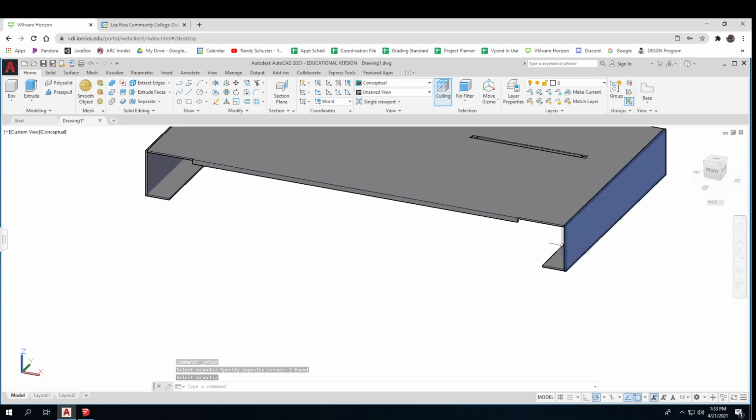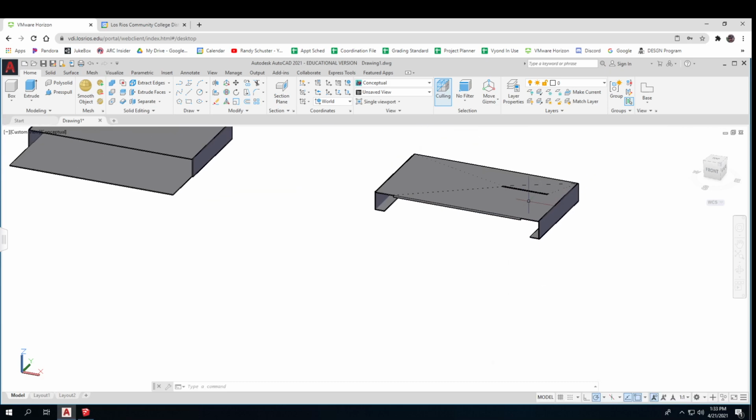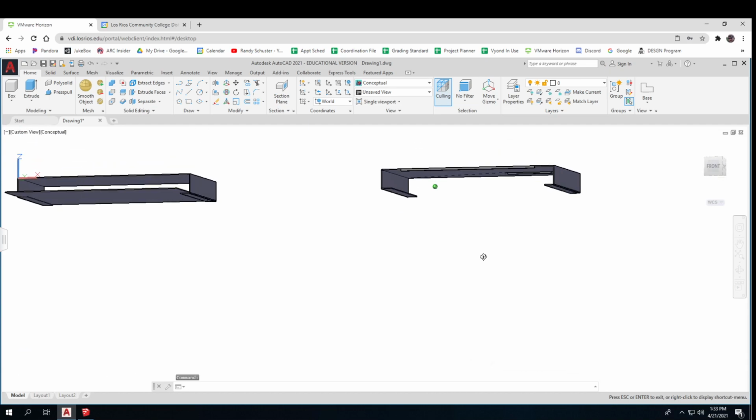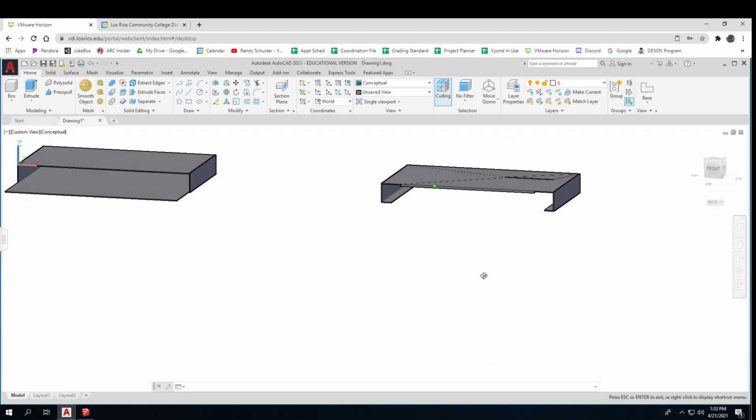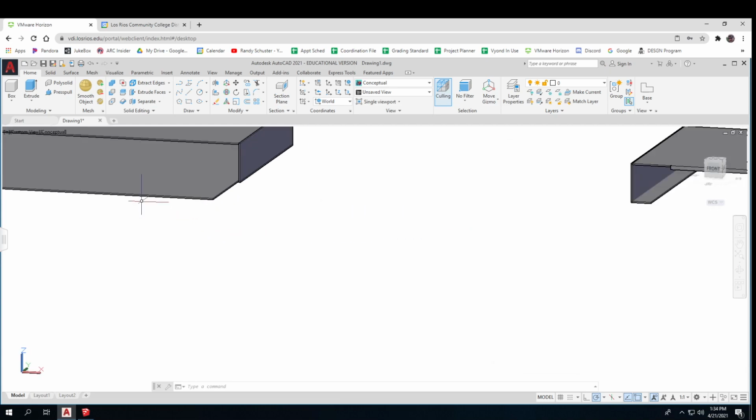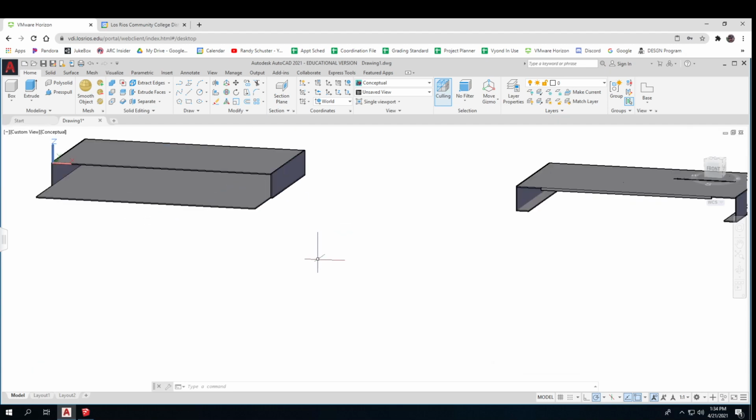Now, as a flat plate, these would just swing out, and I would have my bend. So I can stiffen this with a lot of bends. So that would be a very, very simple piece for them to make in the plate shop. And it would be pretty light. You could figure it out. You could find its total volume and figure out how much it weighs, or you could figure out how much plate it is and look it up. I'm not too concerned with that right now. But you could do the same thing with this bottom piece too. You could put some supports along it.